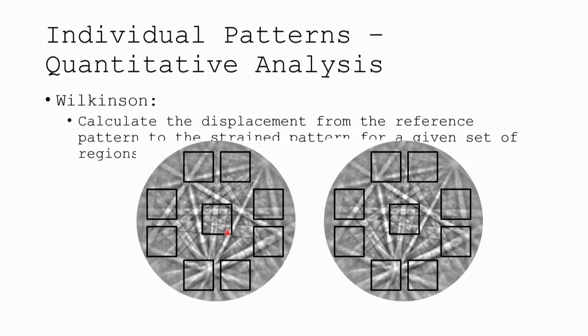It doesn't exist, right? I consider these to be like the physics problems you have in class where you talk about frictionless bearings and massless springs. They don't exist. Well, we come up with some estimates, and the way Angus Wilkinson and the others in the UK do it is by looking in an individual grain and finding the pattern that has the least lattice curvature around it and the highest image quality. And they say, okay, that's my strain-free reference.